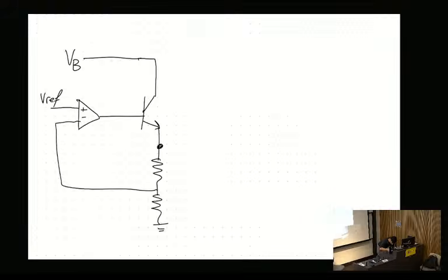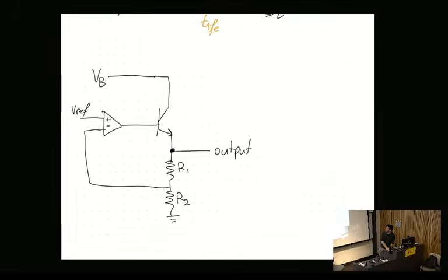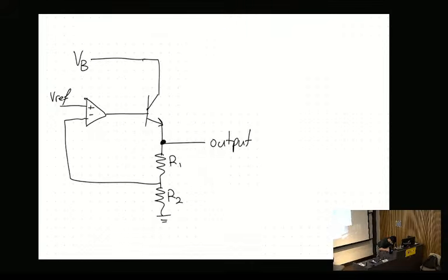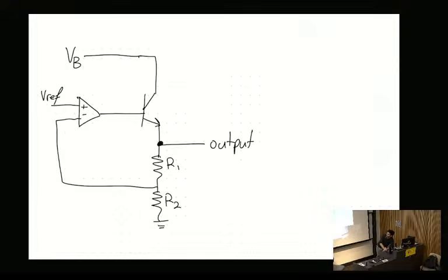And then we take our outputs there. Right? So R1, R2. Now, how this regulates voltage is not too complicated. Although we're not just regulating voltage ripple in this case, we're dropping the voltage, right? So we want it to be 3.3 volts. So this voltage is VREF as well.